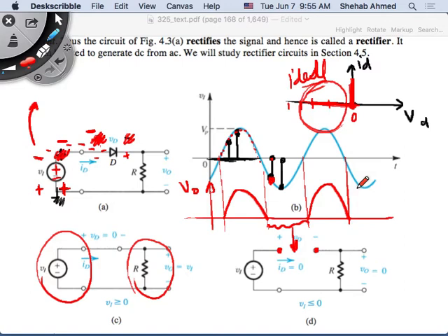So I like to just put DC sources, and say, okay, at this point in time, what do I have? I have a positive voltage. Okay, draw your positive voltage here, and your diode here, and your resistor. How about at this point in time? I have a negative voltage. Then draw a negative voltage, and draw your diode here, and draw your resistor. Okay, so now here is the most positive value in the circuit, which means that this is more negative. So the diode will conduct.